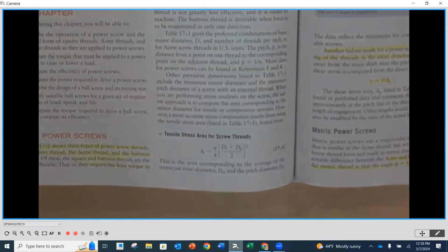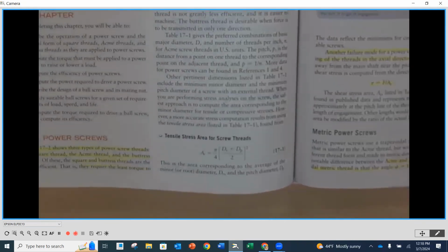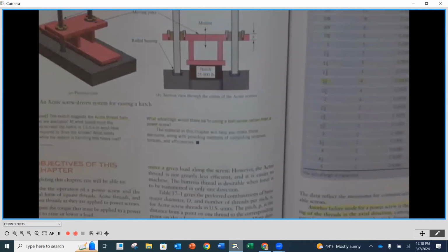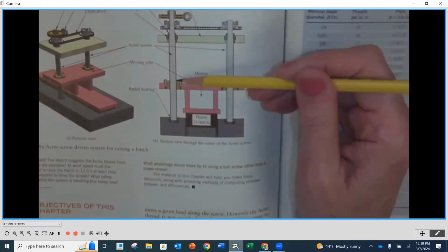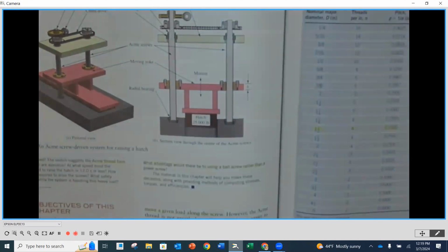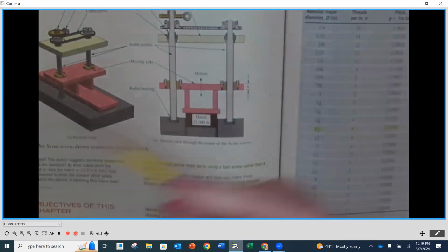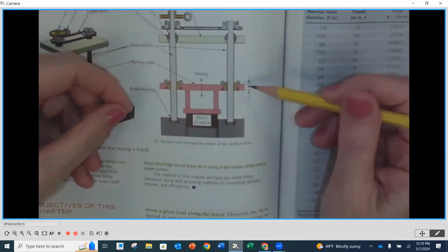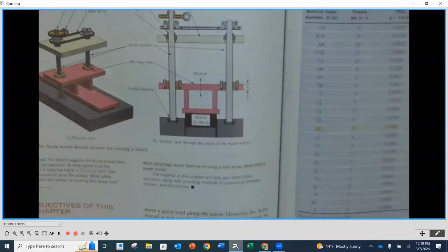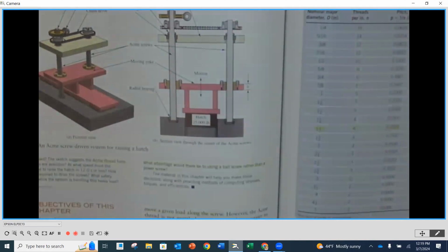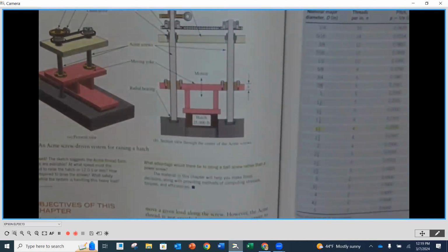As we look at this, and I'm actually going to peek back up here really quickly. Now we have a rod, and what's happening is these are engaged with that nut that's attached to the yoke. So if we're going up and down, you can imagine that we are axially down the axis here. We are going to be either pulling or pushing down on each one of those rods. That's going to be the tensile and the compressive stress that we end up seeing.